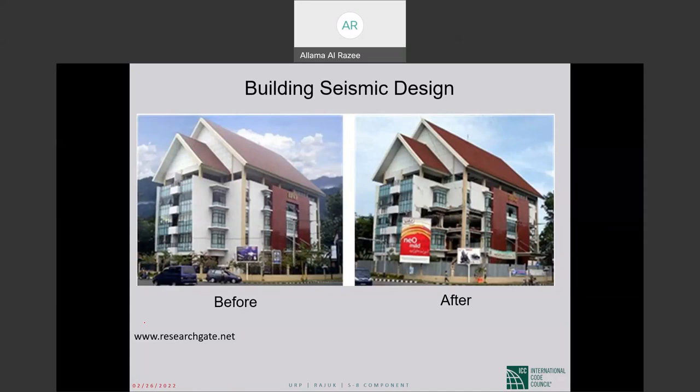Most probably, we can't keep it. Most probably, it isn't worth retrofitting. We should demolish it after the earthquake. But we design for this. We design to just keep its stability and integrity, and even after an earthquake around the design level, it gets damaged, but people don't get that much hurt in the building, and then after the earthquake, we have to demolish the buildings. So we are designing them for the damage.